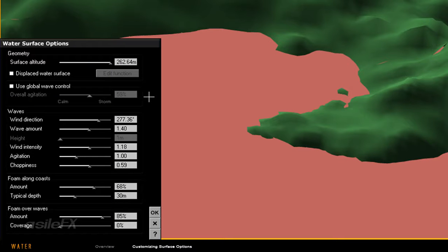When tweaking material options with a displaced water surface, I highly suggest you keep the camera in the same location and not modify the position or rotation options. The reason for this is because after the first displaced water render is done calculating the geometry of the water, this calculation does not need to be performed until the camera is moved or the geometry is modified. This drastically cuts down on render times, allowing quick renders for material adjustments.